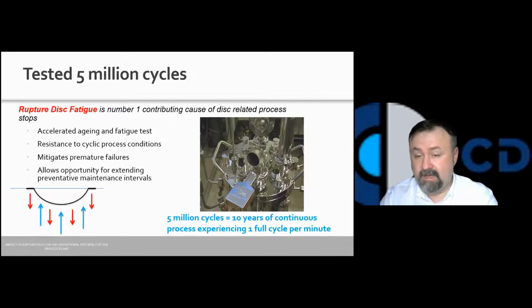So what is it? It's a test that we carried out on the HPX family of products, where we subjected it to 5 million cycles from full vacuum up to the operating pressure of the disk, and then burst it at the end. And the test demonstrated that the disk hasn't been experiencing any fatigue. It burst at the same pressure as its original test results.